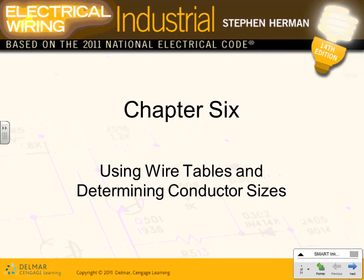Here are a few things directly from the code. This chapter talks about wire tables and determination of conductor sizes. Very quick. When we size wires, you're going to size them based on a few things. Number one, you size based on load, and typically you multiply it by 1.25 because it's continuous. That's load.